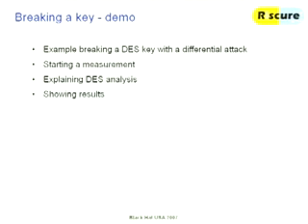Suppose in building the smart card you limit the number of times it can be used, so that by the time we do this analysis, the smart card is probably not so good. Yes. The question is, what if you do just limit the number of acquisitions that you can do, just the number of transactions? That's a way to limit the threat. If you know that your countermeasures are good enough that an attacker needs at least so many measurements, then this is a way to prevent it.